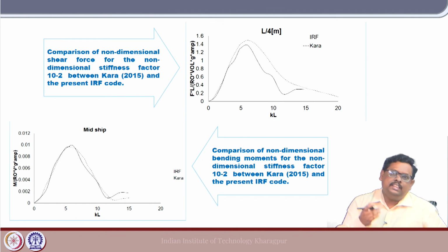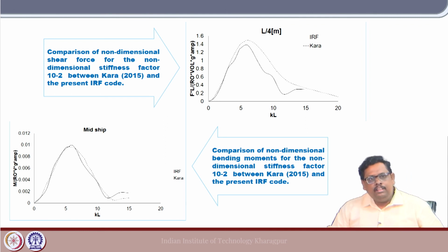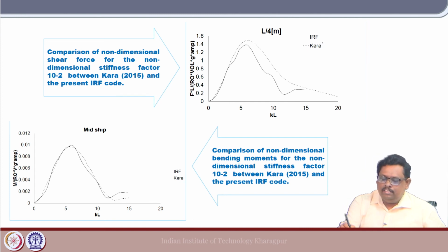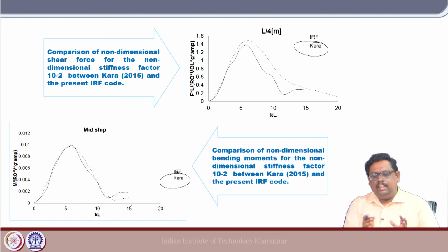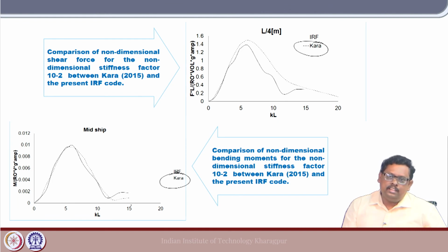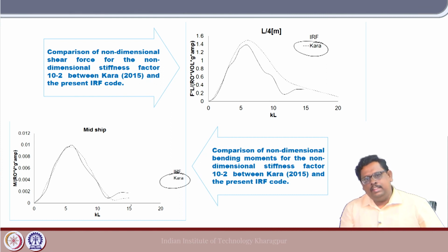So, now this is the result of the non-dimensional shear force and, I think the second one is the bending moment, and you can see that it is matching very well with the published results. Kara used the time domain solution. However, the structural solution is similar. He used the structural solution using the modal superposition. That is how he solved the structural problem. However, he used the time domain panel method to calculate the radiation force, diffraction force, etc.